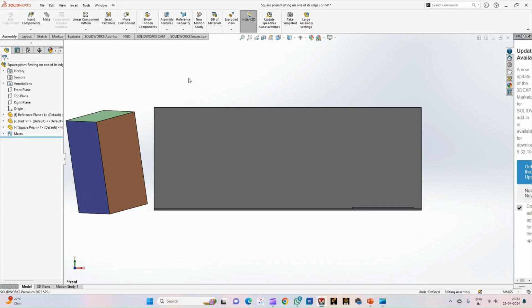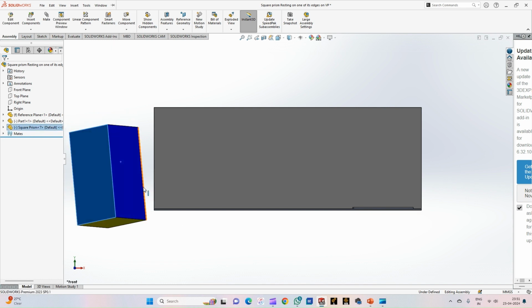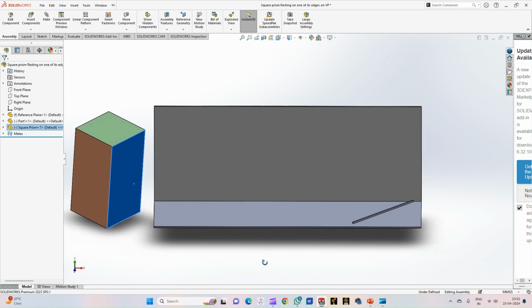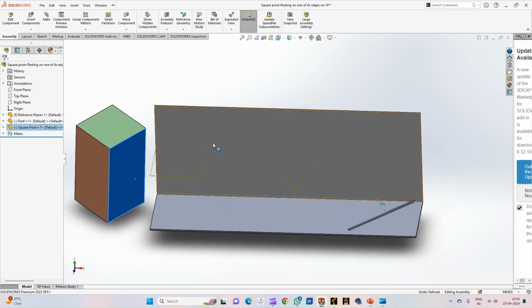We will now try to understand the pictorial representation of the orthographic projection of the solids. Here, the type of the prism is a square prism, and as per the problem statement, it has a side measuring 35 and the axis length is 65. As you can see, this is a square prism, which has a side of 35 and an axis of 65. Now we will consider the two planes for better understanding. This plane is the vertical plane where the front view is recorded, and this is the horizontal plane where the top view is recorded.